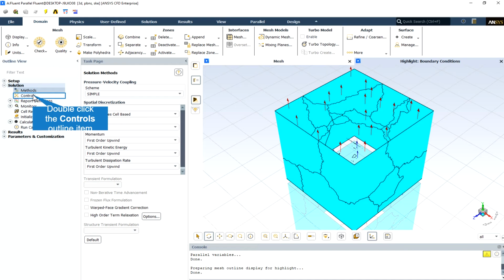quadrilateral or hexahedral meshes, or some cases just like in this present CFD simulation of double facet, the numerical diffusion will be naturally low, so you can generally use the first order scheme instead of the second order scheme without any significant loss of accuracy. Finally, if you run into convergence difficulties with the second order scheme, you should try the first order scheme instead.